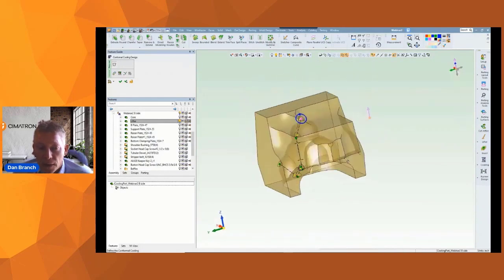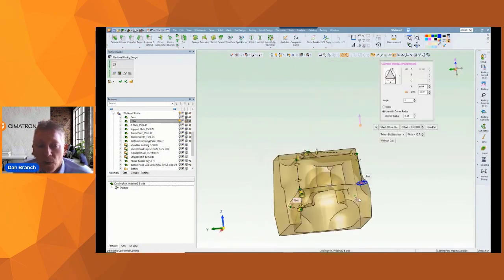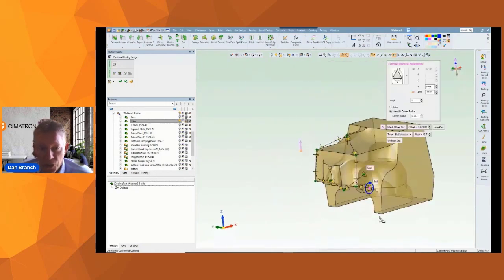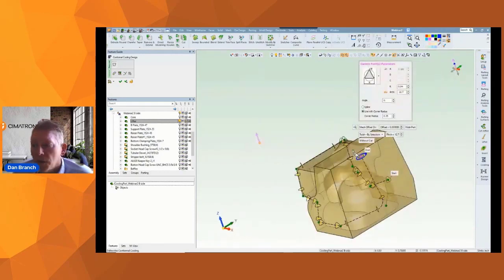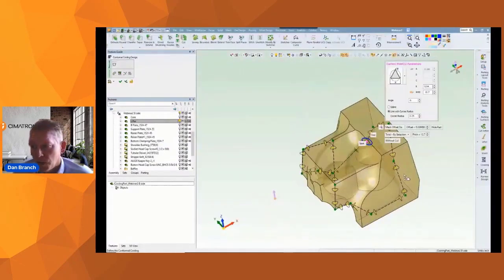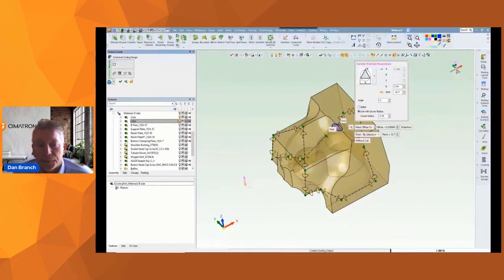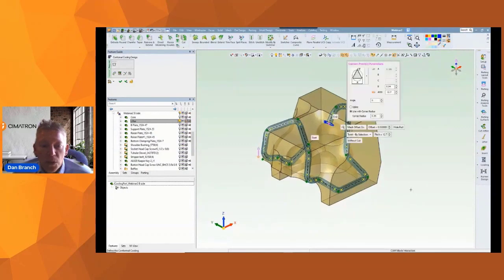At every point along the path, the section is previewed, and I have that dialog available. So that provides for a huge amount of adjustability in the channel size and the channel shape. You can even turn on a parameter to continuously twist the channel. So that provides even more variety in turbulent water flow. I'll preview it, and that would be the proposed conformal cooling channel.